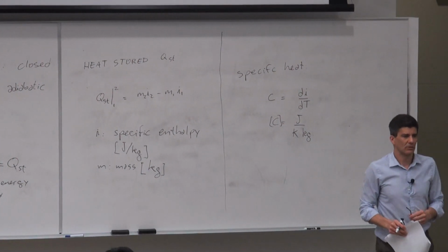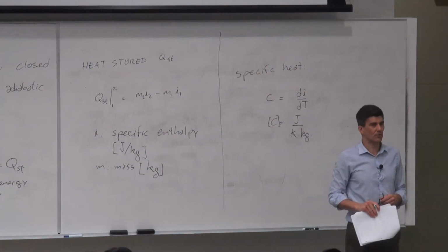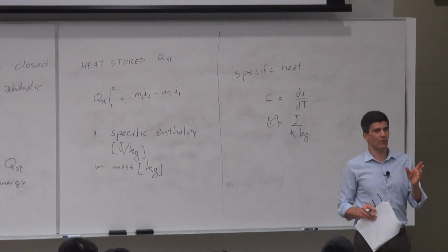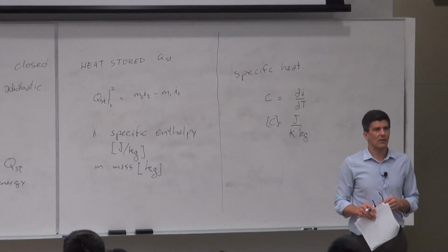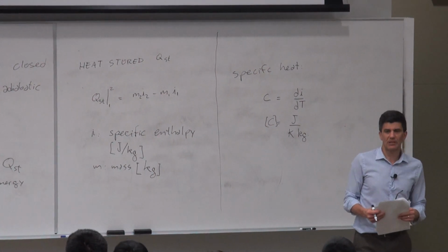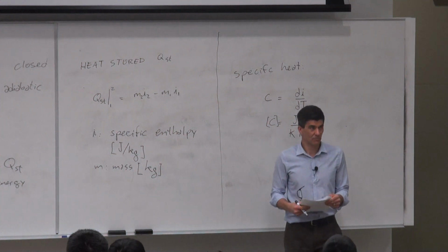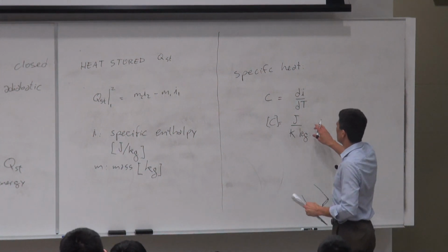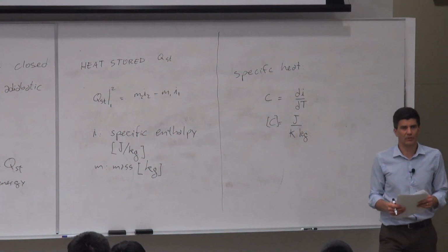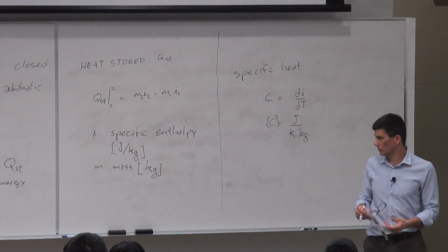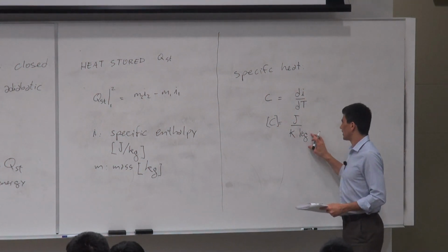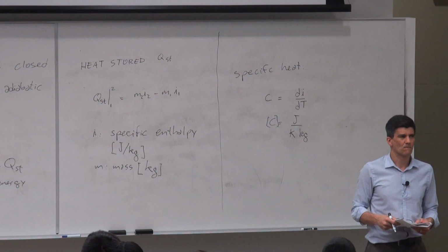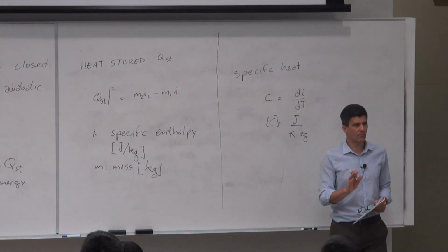So I used to put a lot of emphasis on unit conversion in the past. That didn't make me any new friends. But let me tell you something that is important. If I tell you it's 20 degrees, and it's 20 degrees C, it's awesome. If it is 20 degrees Kelvin, you better get a good jacket, right? Okay, but if I say my specific heat is 400 joules per kilogram Kelvin, or if I were to say 400 joules per kilogram degree C, are those two numbers the same or not? They are the same. And this is a super important thing.